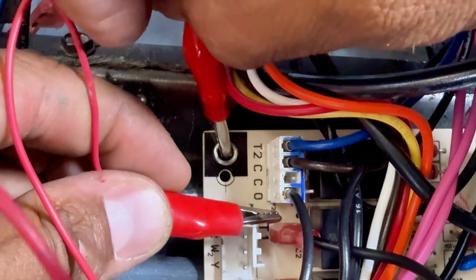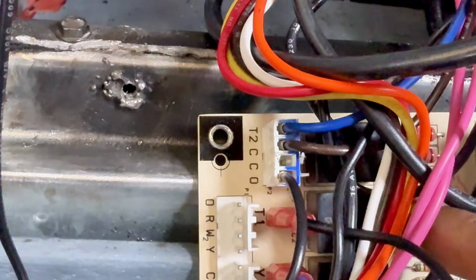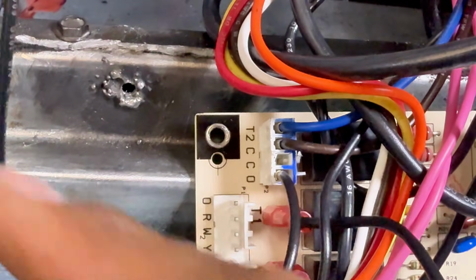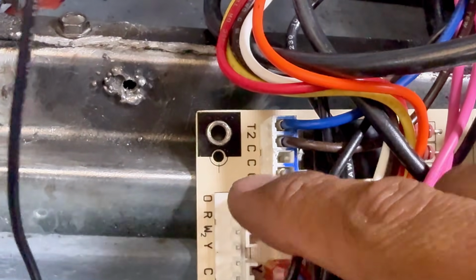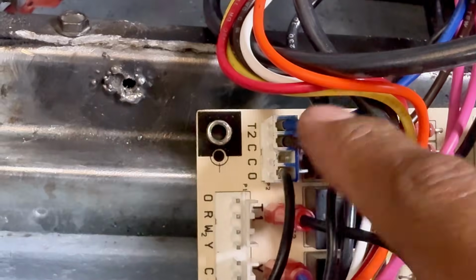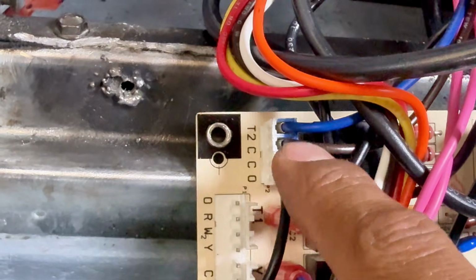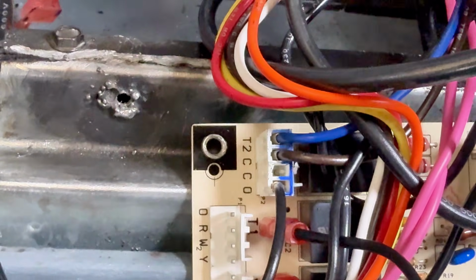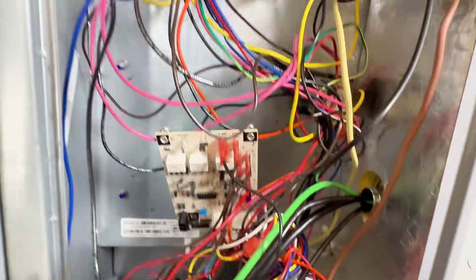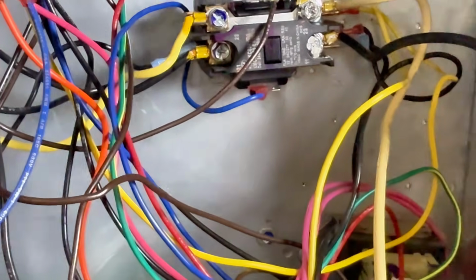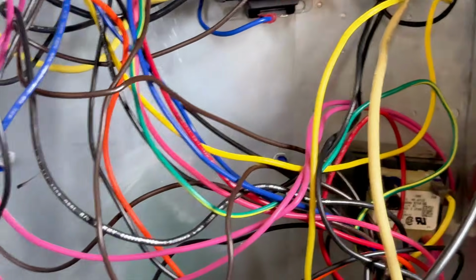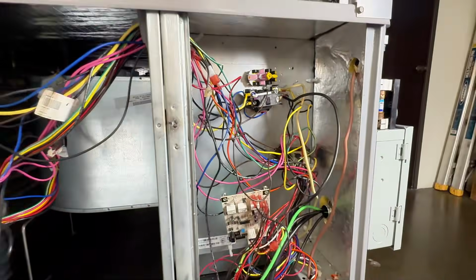T1 and T2 internally. It then routes the 24 volts because the pressure switches were closed. It goes here, it comes out in the blue. And the brown one is my common. Common, 24 volts. So now look at that blue one. That blue one goes to my contactor coil.